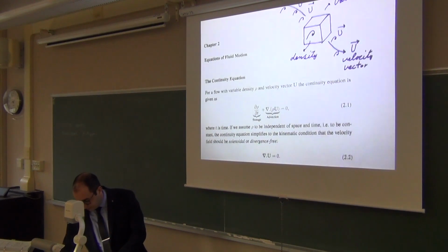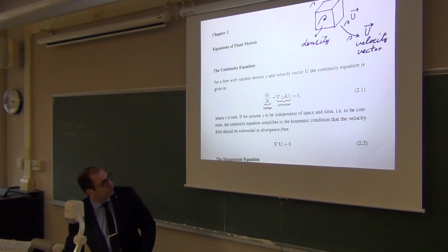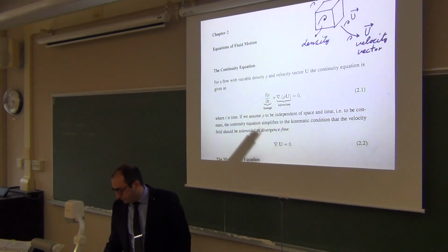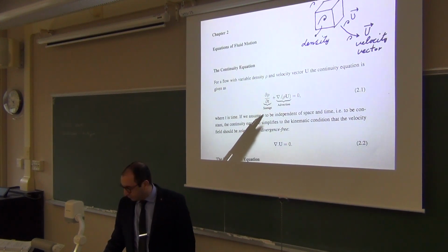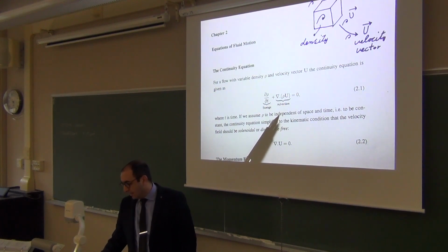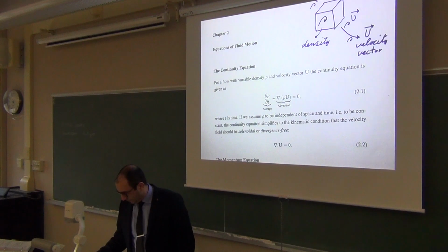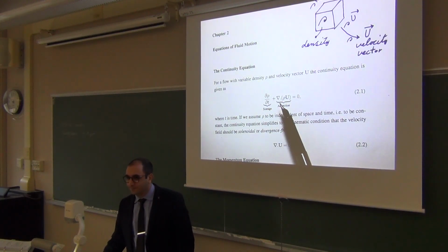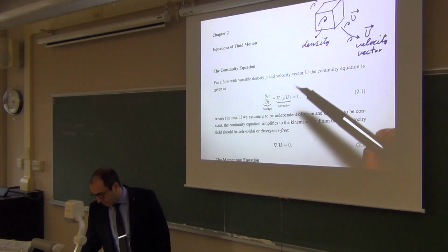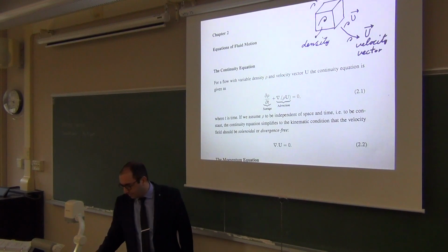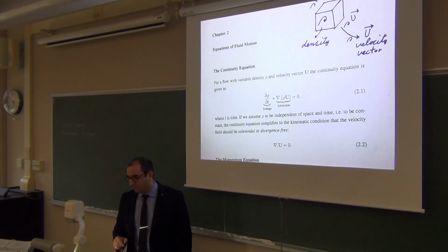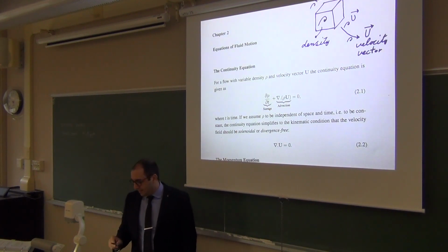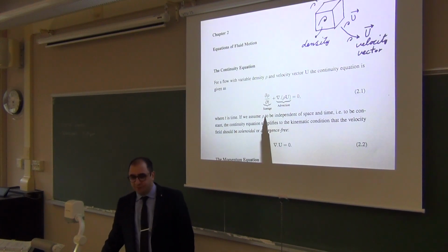The equation that expresses this change is the following. It's the continuity equation, where you have the rate of change of density, with respect to time, in this control volume, plus another term, which we call advection. What is the symbol? Inverse delta or nabla. Yeah. So nabla dot rho u. This equation is the equation for the conservation of density. It consists of two terms: the storage term, or rate of change of density in the control volume, plus the advection. Basically, the net exchange of density at the boundaries of this control volume.